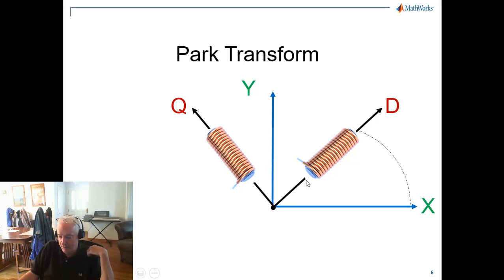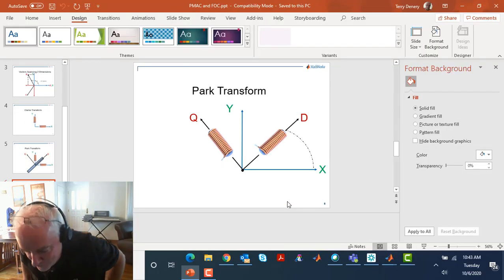So then what I thought was really amazing is that these predecessors to us, and I guess Park and Clark were two of them, but I'm sure that Tesla was very well informed on this idea too, of the importance of D and Q. But this recognition that this perpendicular axis is entirely responsible for the torque that can be produced by an electric motor, and that even more importantly, the torque that's generated by the motor, based on the windings and all that kind of stuff, is going to be proportional to the current that flows through this Q axis, right? And so with that, hopefully I gave a reasonable introduction to field-oriented control.